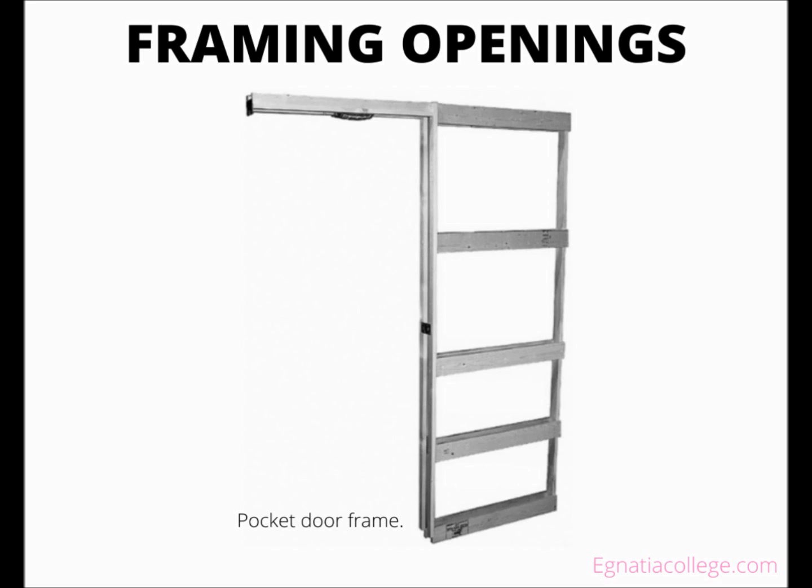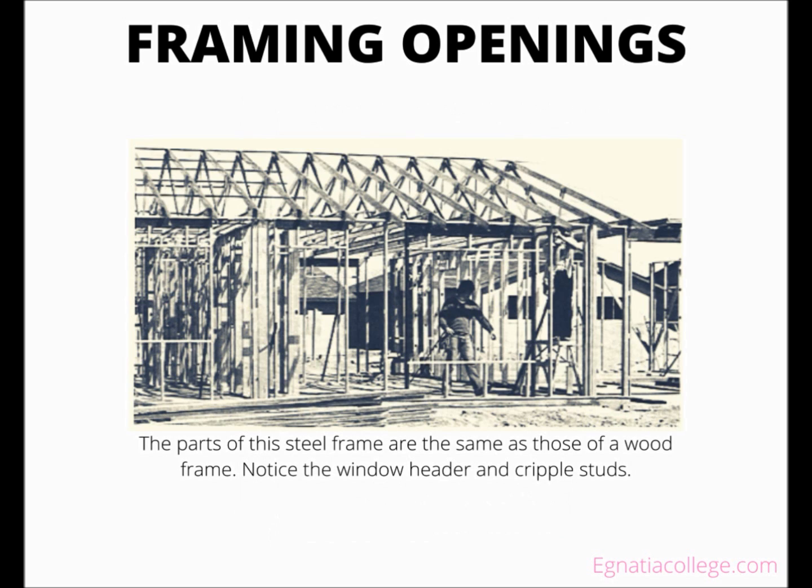Several systems of metal framing are available for light construction. The basic elements of light gauge metal framing are the same as for wood framing. These systems use top and bottom wall plates, studs, and floor joists. To make light gauge framing compatible with wood, the metal members are made in common sizes for wood framing. The greatest difference is that metal framing is joined with screws instead of nails.